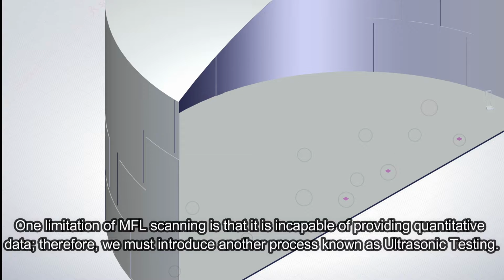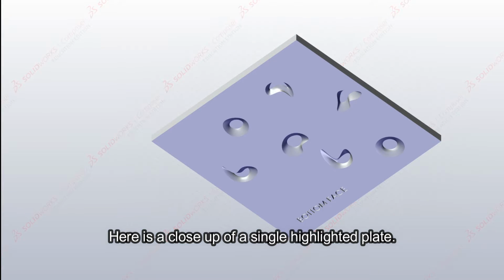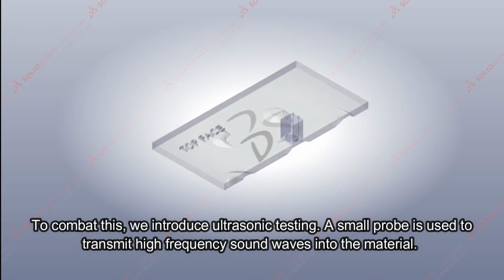One limitation of MFL scanning is that it is incapable of providing quantitative data. Therefore, we must introduce another process known as ultrasonic testing. Here is a close-up of a single highlighted plate. As mentioned, the corrosion seen here is not visible to the operator. To combat this, we introduce ultrasonic testing.